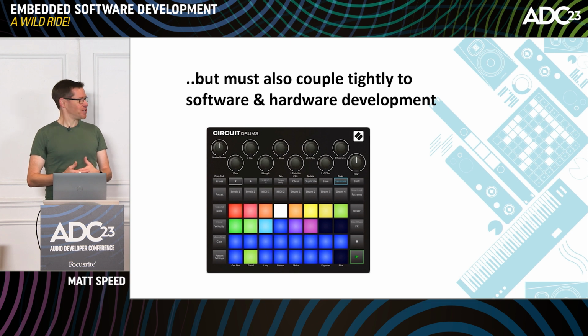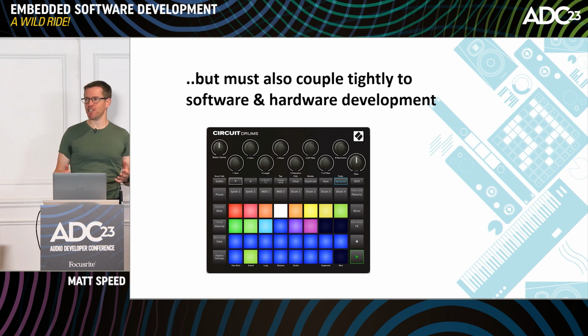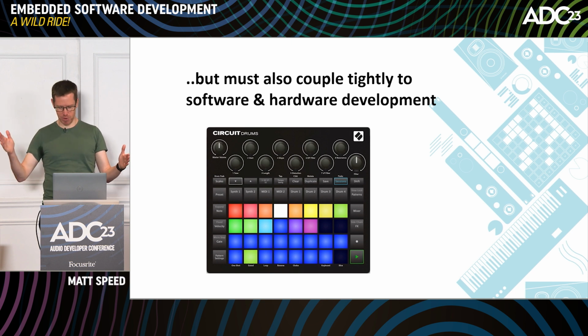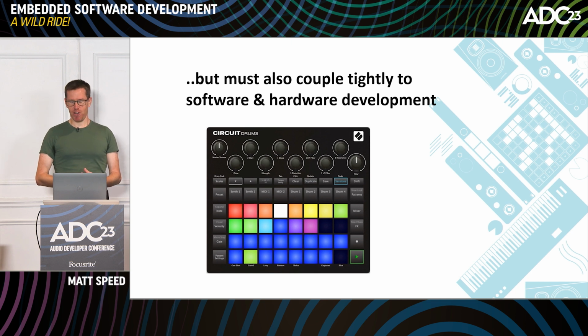There's a real risk of a kind of big bang integration event where, at the end of a project, the software is complete and the firmware is complete, and then you stick the software on the firmware and you run out of RAM. Or you run out of clock cycles, or something doesn't work as you expected, and it doesn't go well. You really don't want to find that out a few weeks before you ship. Bad times.